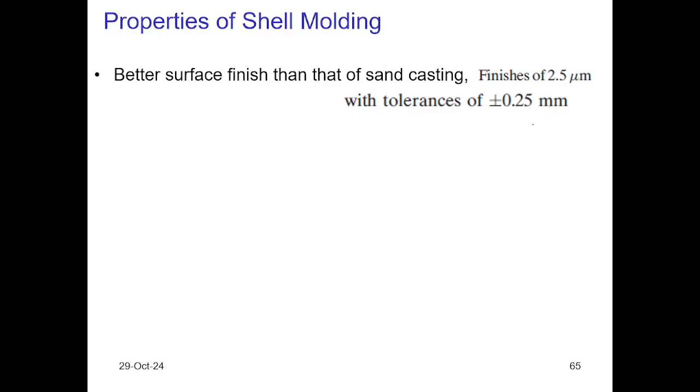It is a better surface quality. And the manufacturing tolerance in setting the size of the features is smaller, 0.5 millimeters. You know, these are the upper and lower deviations. Lower deviation plus upper deviation is the tolerance.